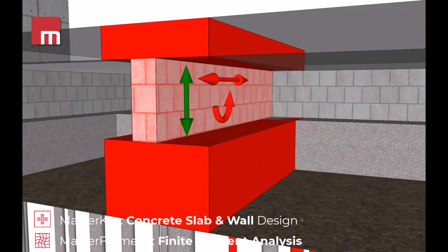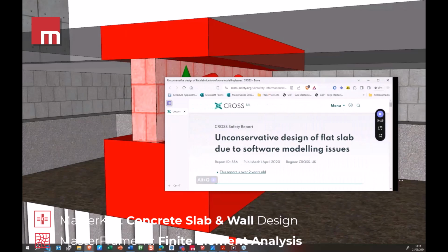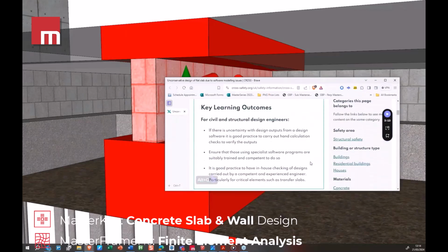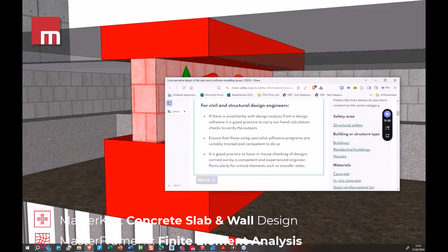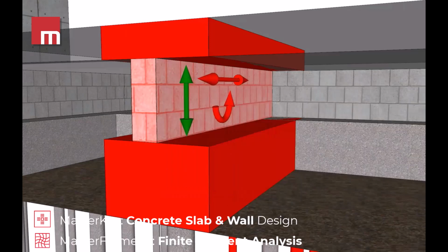So hopefully with a bit of background and understanding of beam behaviour and the different associated stresses, you should be able to understand the issues with this approach. And so referring back to the report, it is suggested to alternatively model the supporting walls as a series of pin-ended columns within the model at close centres to simulate the vertical load transfer.